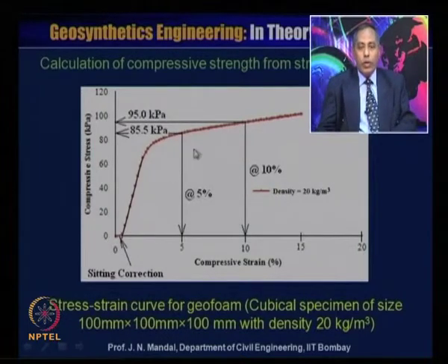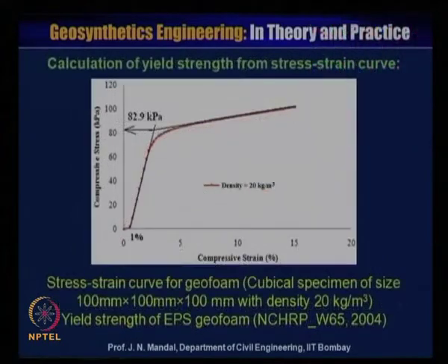So, this is also very important: when we design geofoam material for any structure, we will consider what the compressive strain should be for a particular strain value, and particularly for 5% and 10%. So, now, calculation of the yield strain from the stress-strain curve.